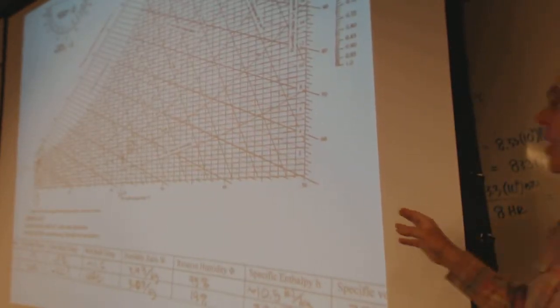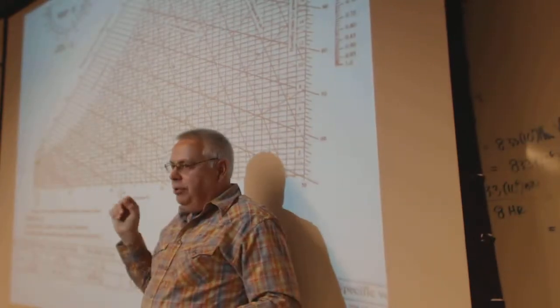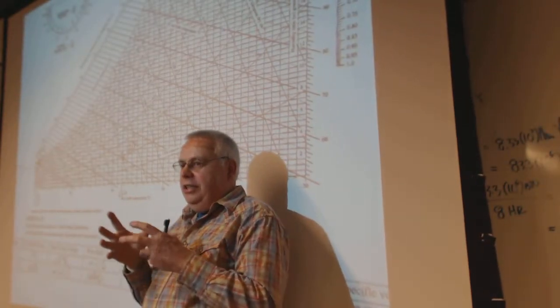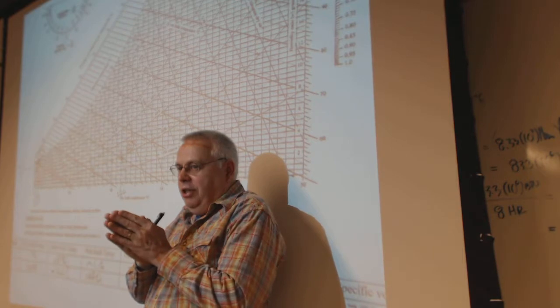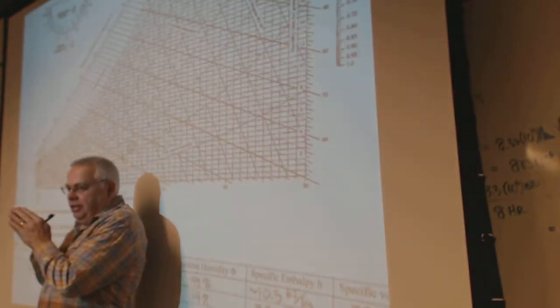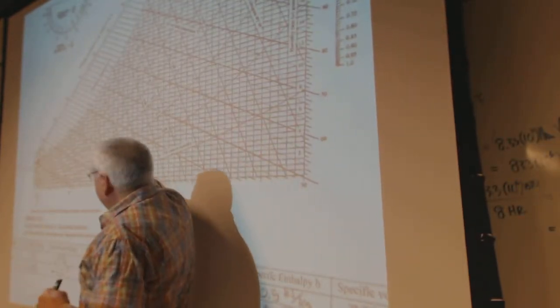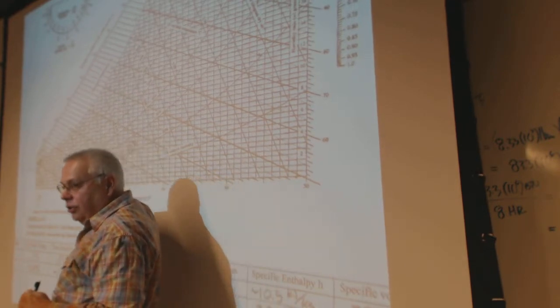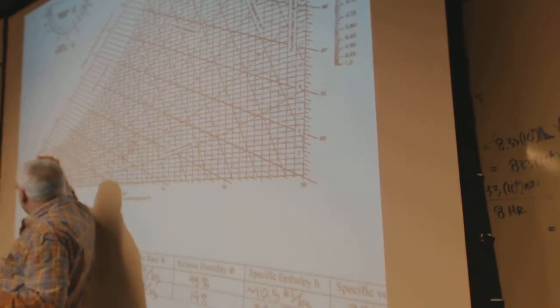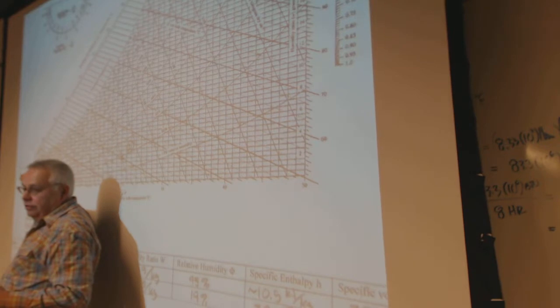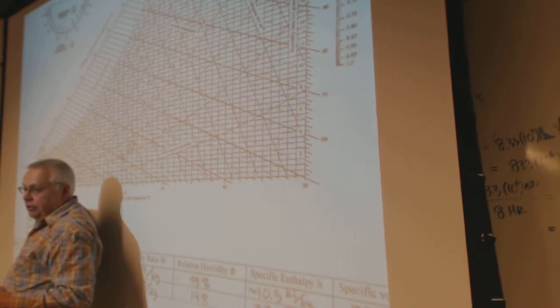Yeah, so one more time. The dew point is when you actually condense, so you're taking that partial pressure and driving the temperature down until it becomes a saturation pressure. So the moisture content doesn't change. You're cooling it, so you go horizontal until you hit the saturation curve to find the dew point temperature.